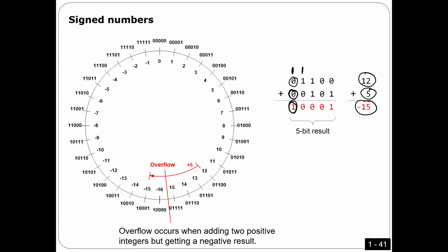The other approach, you don't need to care about it now, but just for learning, because we're going to use it later. Look at the most significant bit. There is a carry input coming here, so C1 is equal to 1. However, there is no carry output here. I'm going to call it C2, whatever the name. I'm going to compare the carry input and the carry output. If they are different, that means there is overflow.